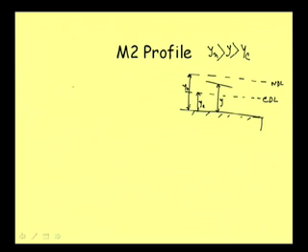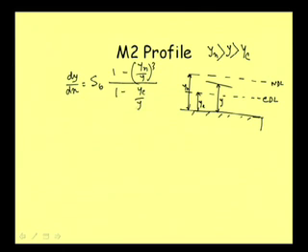Now, if we refer the same equation, that is dy dx is equal to Sb into 1 minus (Yn by y) whole cube divided by 1 minus (Yc by y) whole cube. Let us refer the same equation. Well, and here also as it is mild slope, so Sb is positive, Sb is less than Sc, but it is positive, it is positive.